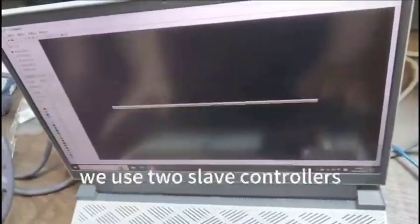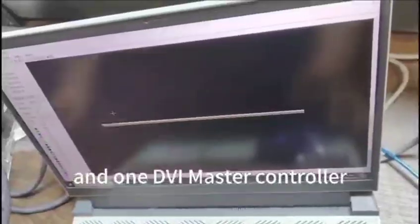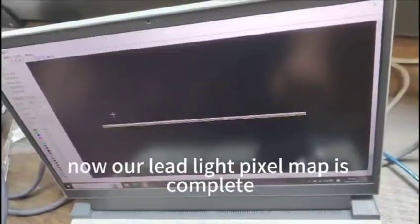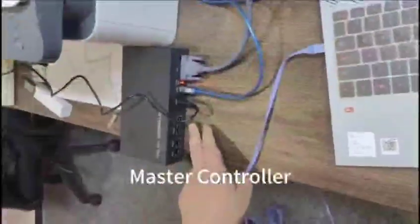As you can see, we used two slave controllers and one DVI master controller. Now our LED light pixel map is complete. Now we can proceed to the next step. The second step is to send this map file to the DVI master controller.